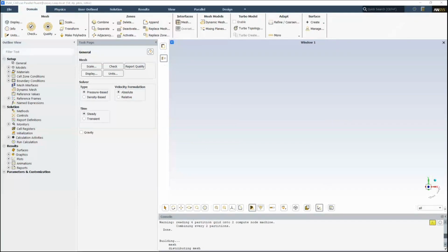We're going to look at things like heat transfer. We're going to look at some solver settings. All of the different ways you can find errors in a CFD simulation, because there's a lot. And then we're going to go through some post-processing, some simulation review. And if we get a chance, I'll take you through some more advanced models that we've built here based in adjoint solver and based in things like overset meshing.